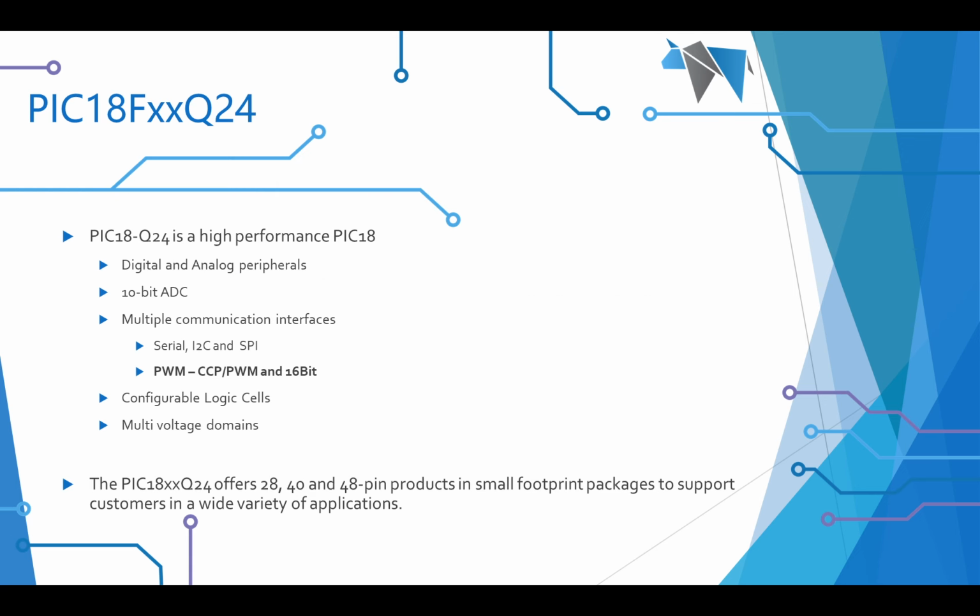What we're looking at is, as in bold, that's like the sixth bullet down, pulse width modulation, PWM. There are many ways of doing that, not only within the capabilities of the chip itself, the Q24, which is a high performance PIC18, but there are other ways within the language of GCBASIC that support generating signals that look like pulse width modulation.